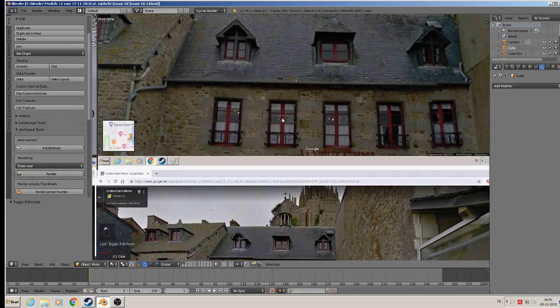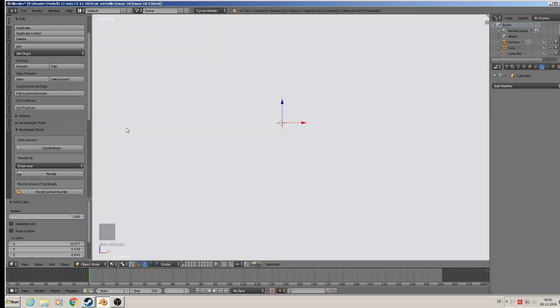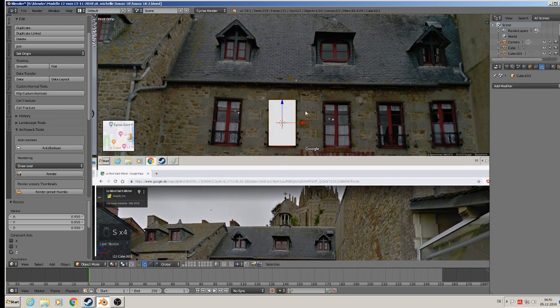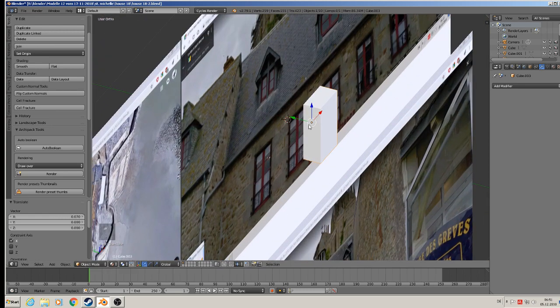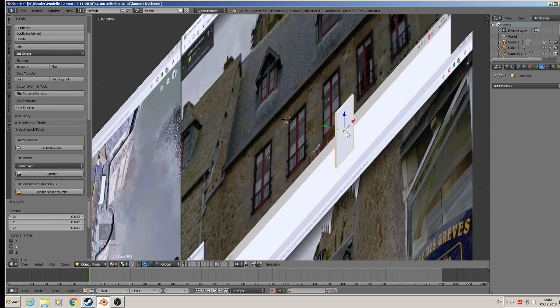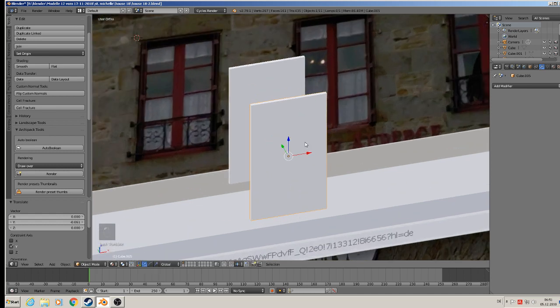So we start that. At first we need the glass itself. So add mesh cube, scale set, scale. Okay, the glass should not be so big, so scale Y, only a glass, not more, not less. So, okay. Then Shift D, make a copy of that, and there we have to plug in this stuff there.